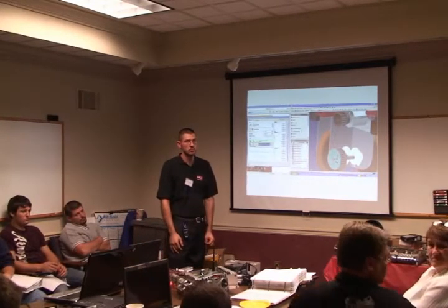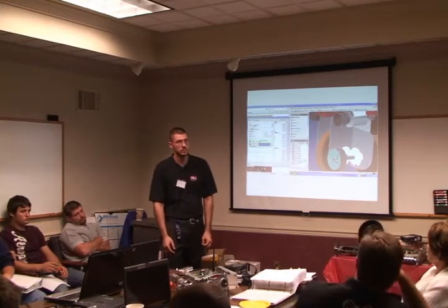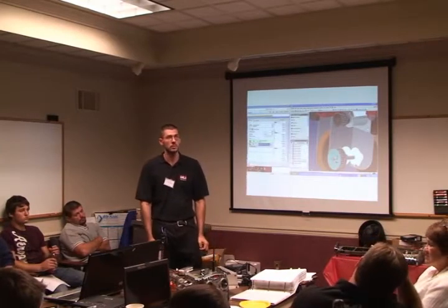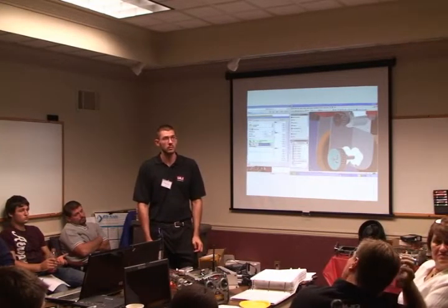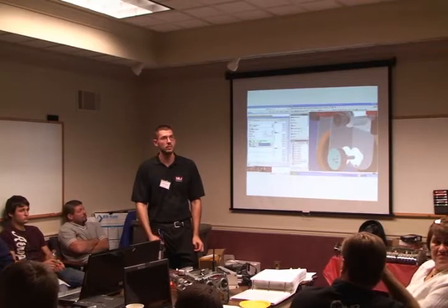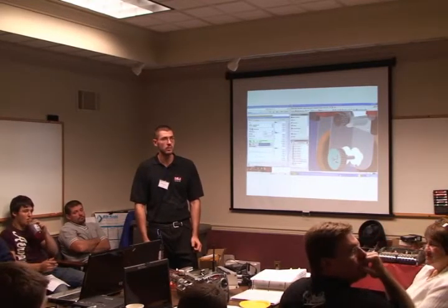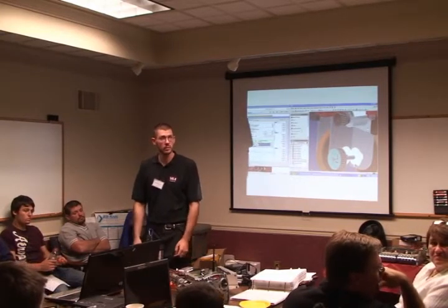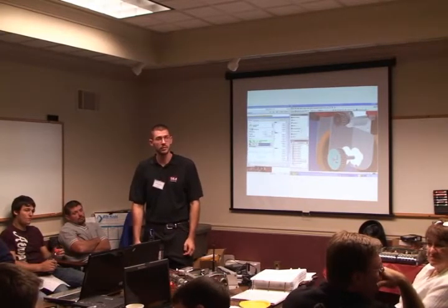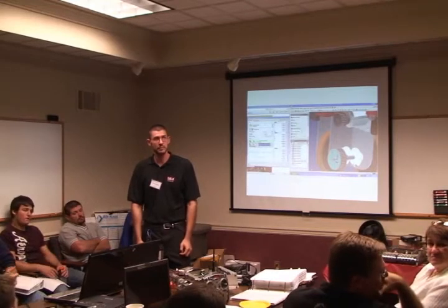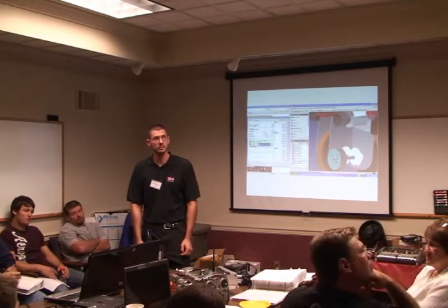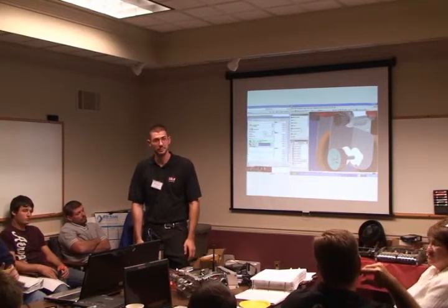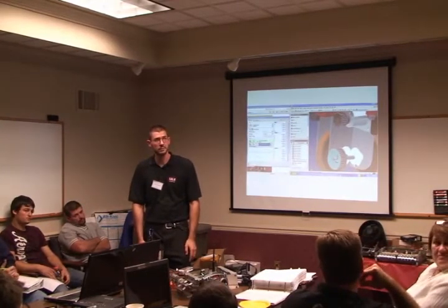It'll draw it in. Important whenever you design is to get the spacing center to center on those, because these belts are only available in increments of somewhere around 1 inch. You can't get them every quarter inch, half inch. So that's something you want to consider whenever you design your robot, the spacing on wheel centers or weapon to weapon motor mount, so that you can avoid idler pulleys. You definitely don't want to use an idler pulley or a tensioner pulley on a weapon belt due to the RPM. Good luck finding a bearing for that.